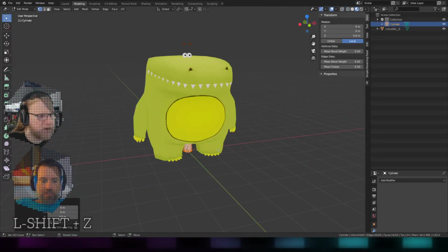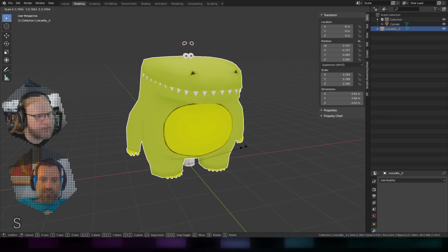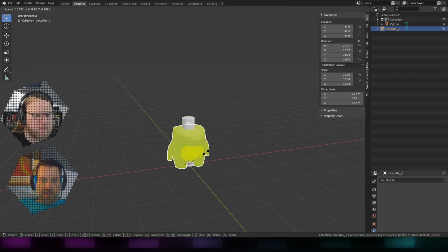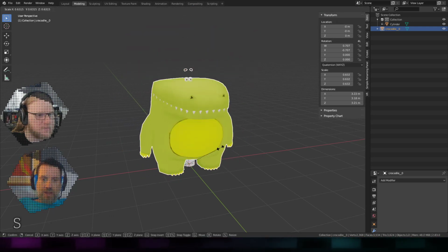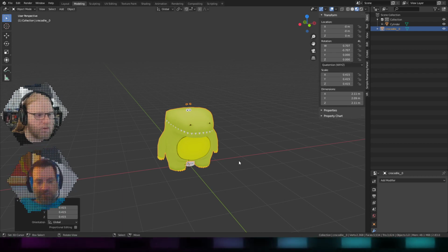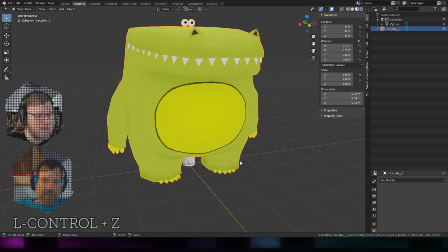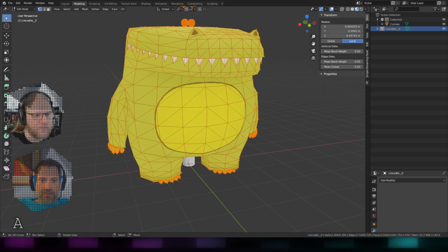He's just big. So we really can scale them down. Of course you can select it and scale it, and now that the pivot is down there, that is a little simpler. But it's actually kind of a problem when you do that, because your scale is now going to be at a strange number and you'd have to reset it. So what I do is I do that in edit mode. I hit Tab, hit A to select everything, and then I go to scale.